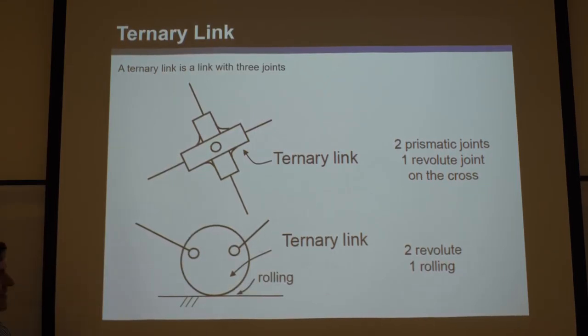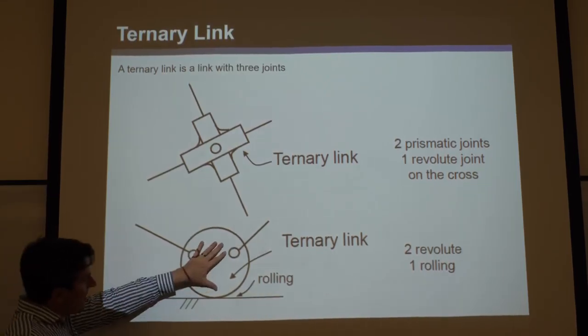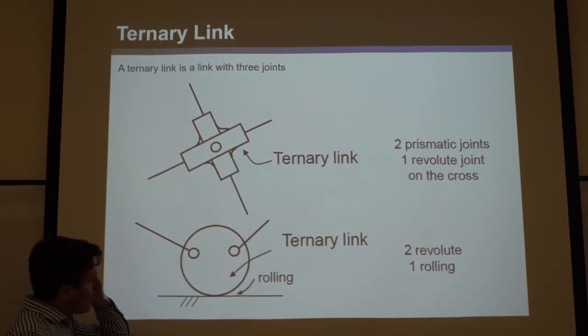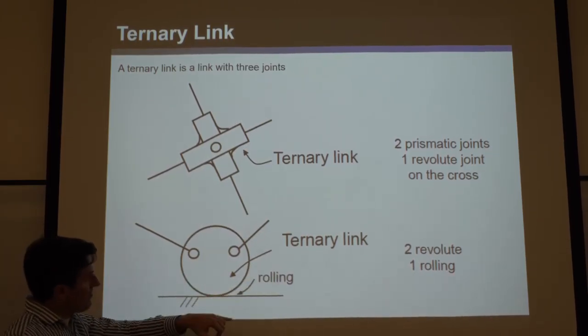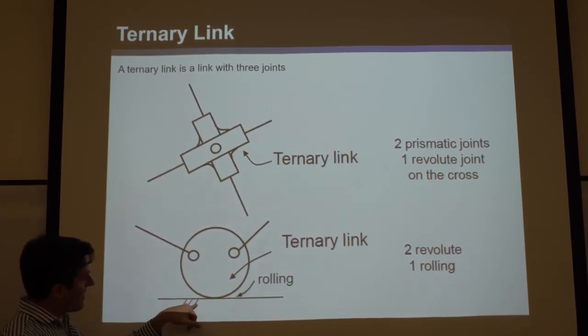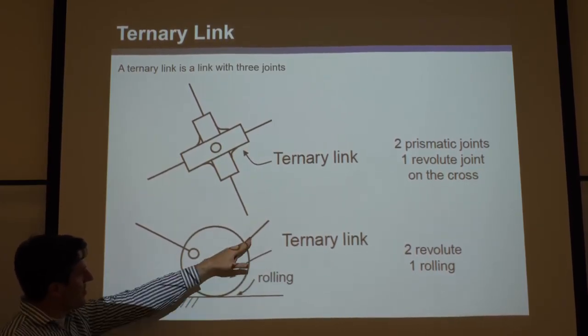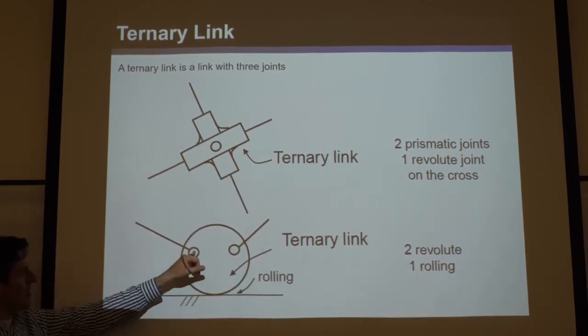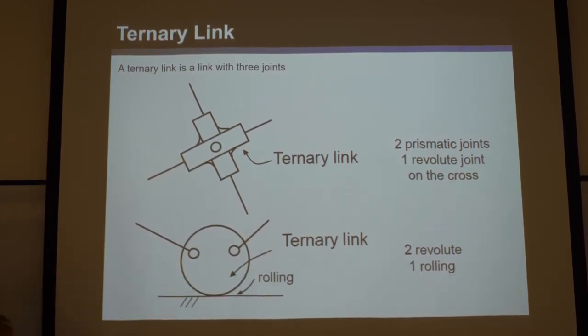Okay. Now this guy here, this circle here, which says it's pure rolling, right? So it might be a gear or something. It is connected to this grounded point. It's ground because of the hatching there, and then 2 other links there, by revolute joints. Okay.